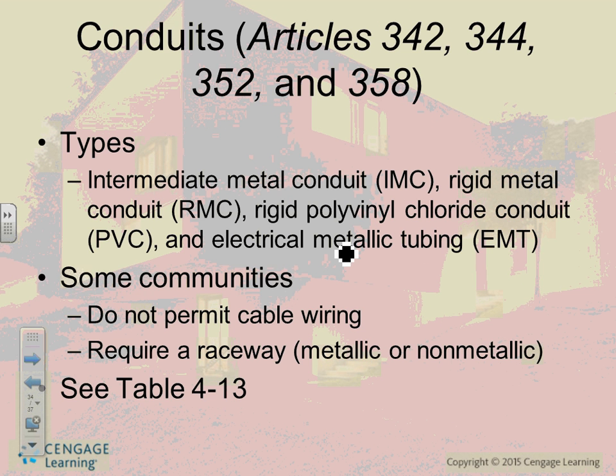When they have a clamp, they either have the clamps rated for one cable or multiple cables. So the inspector will catch you if it says one cable clamp and you put two cables underneath it. Oops, no, we have to remove it. So be aware of the rating of the clamps. Typically they are for two cables, so here you have to put one cable under each one of them. But if you break it, then you can put as many as it fits. Because now you staple it, remember you're stapling it 8 inches from the box, not 12 inches.